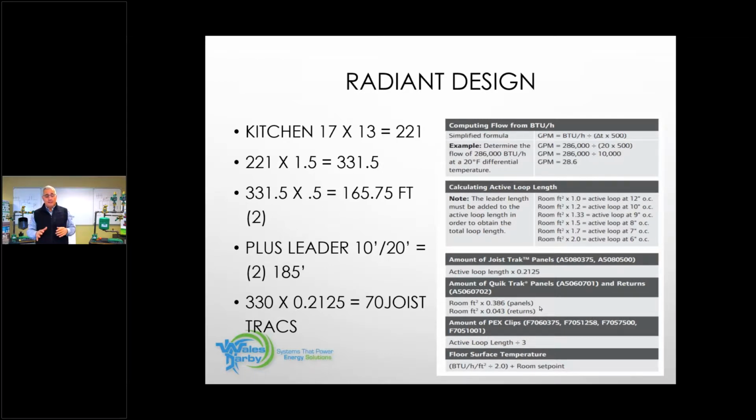So we always insulate under radiant. And the minimum I want to see is R11. All right, that's pink insulation, R11 as the minimum. And make sure at the end of the bay, at the face of the joist there, at the floor plate of the building, you've got insulation there so we don't lose BTUs out at the end of the bay. I hope that answered that person's question.